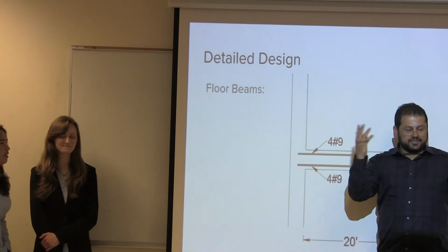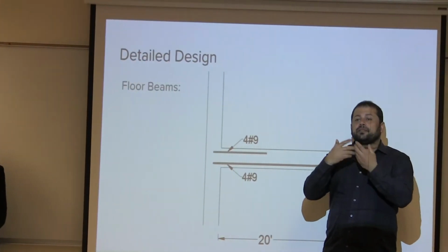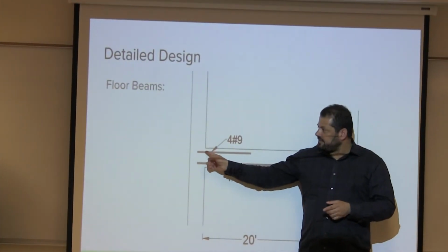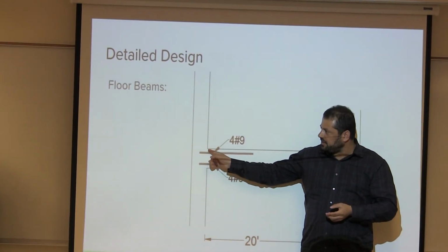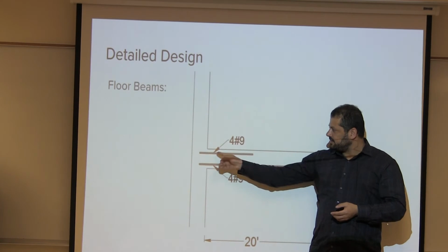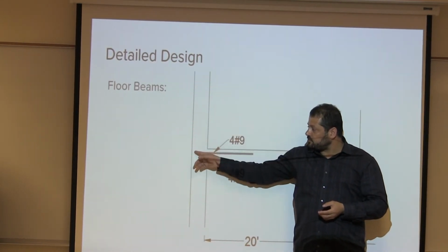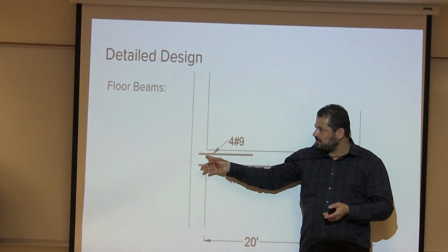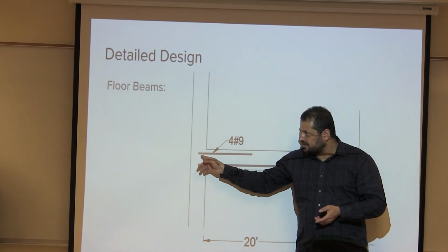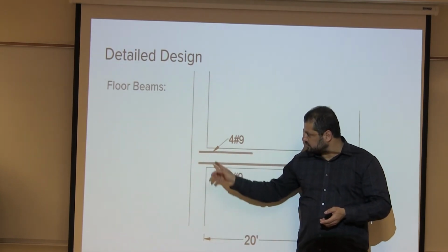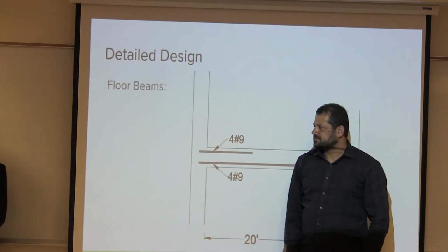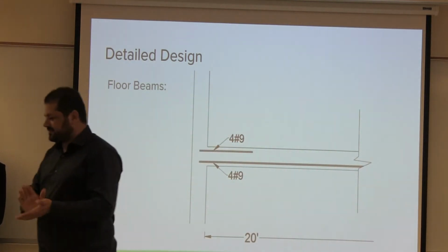Okay. Again, let me explain. The development length says this: if it's a negative moment, when you did the analysis, it must give you a Fy in here. So this side and this side must be enough to develop a Fy in here. This will not develop anything. You need to hook it, either this way or that way, to provide a Fy in here from both sides. Okay, good job, guys.